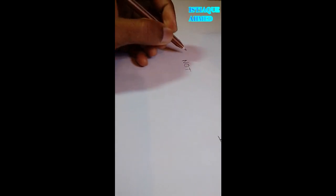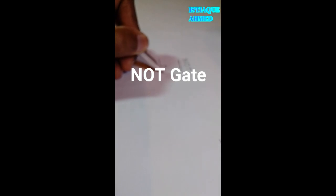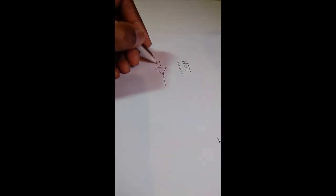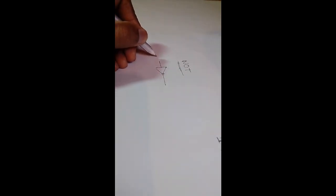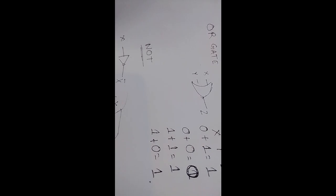These are the basics. The NOT gate is just an inverter. If we give one input and one output, and we give an input X, the output will be X not, or X bar. If we put 0, the output will be 1, and if we put 1, the output will be 0. These are the basic gates.